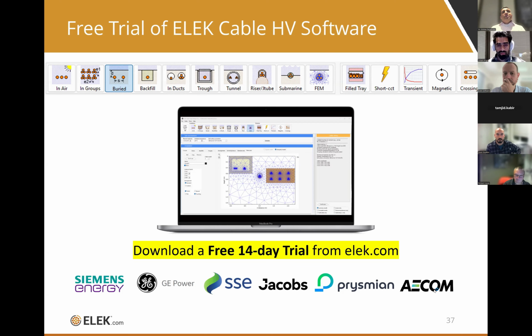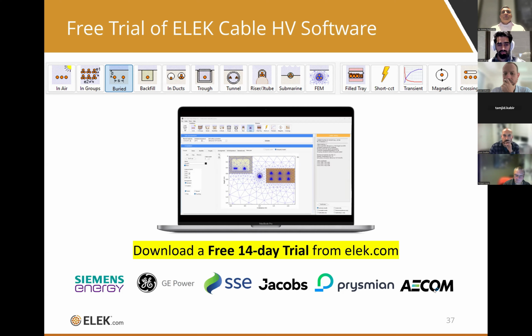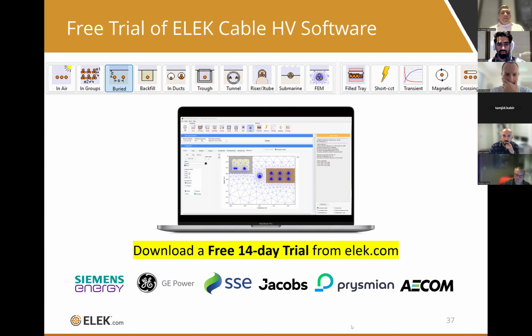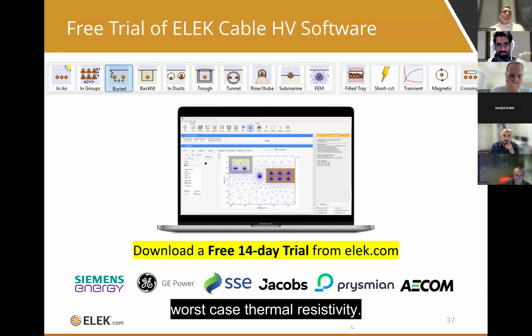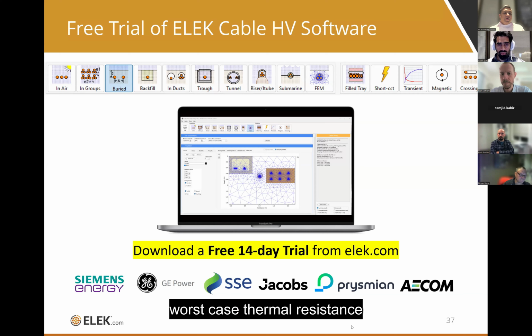We are not doing it now, but we are coming up with an algorithm which can give you an effective thermal resistance for the soil. It's a method called conformal mapping. Using that, you can come up with an equivalent soil model when we want to do an HDD installation. Along with seasonal variations, we have not done anything on seasonal variations, but what we would recommend is to use the worst case thermal resistivity if that is known. You can do measurements and then take the worst case thermal resistance of the soil.